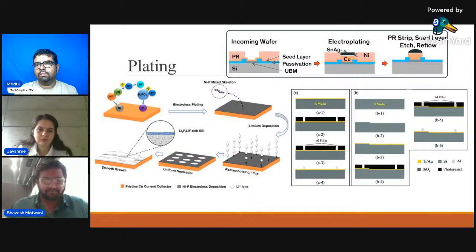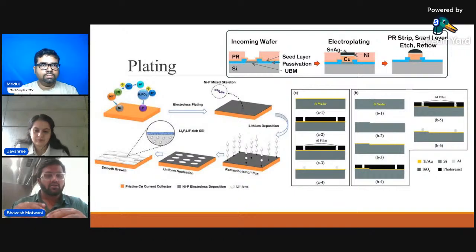As you can see in this first image, we do the electroplating. Like we generally do a chemical reaction, either CVD, which is chemical vapor deposition. We do a thin layer of metal, and then we do the redistribution layer. We form small pads on it, and then smooth it, like do the CMP, chemical mechanical polishing, to make a uniform layer, to form those bond pads to connect the wire bonds.